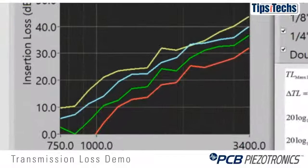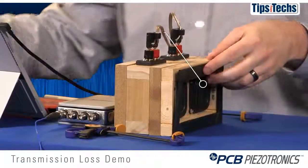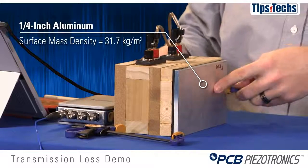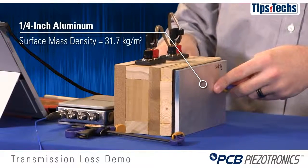And you can see the difference in the green and the yellow curves here. And there is about a 5 to 6 dB increase from green to yellow, as the mass law would predict. Finally, we'll go to a very heavy material. This is now our 1/4 inch aluminum. We would expect this to block a lot of the sound.